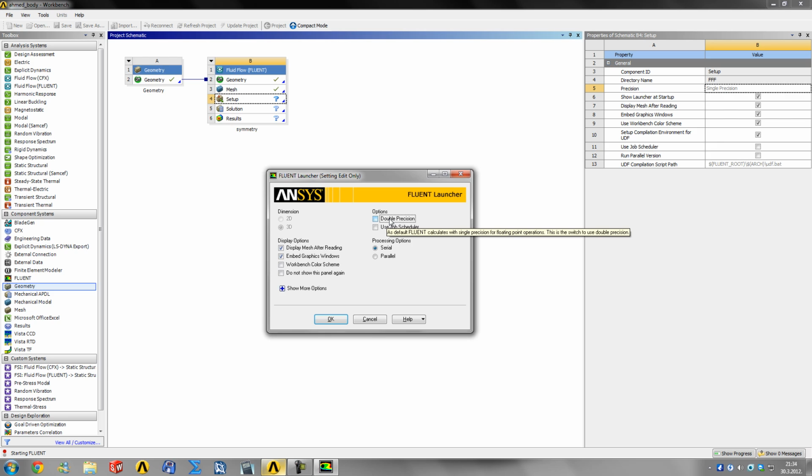In the Fluent documentation there is data where they recommend double precision if you are doing anything with geometry which is very thin in one direction and very long in the other direction, to capture it. Or if you have very small cell sizes ranging to very large cell sizes in a single mesh, then you also need double precision, but you can compare and research for yourself.